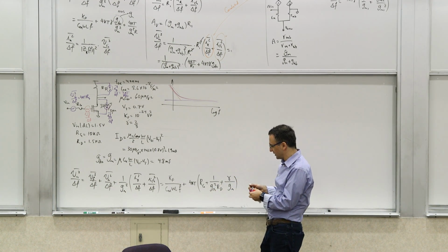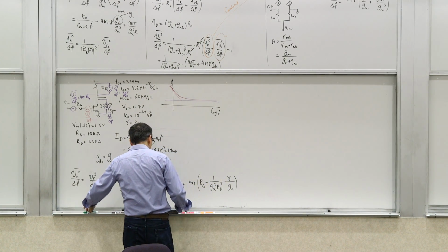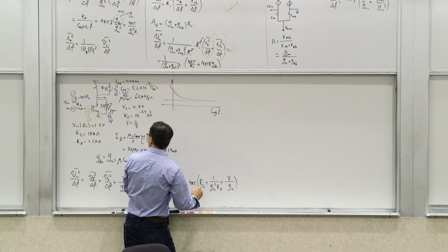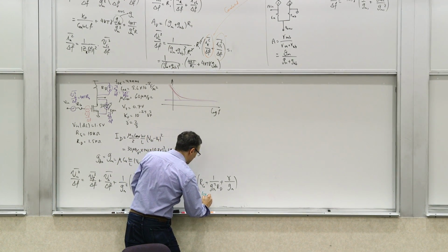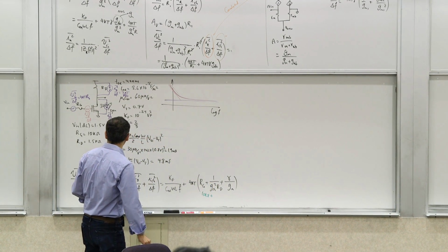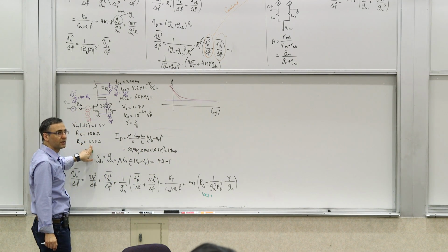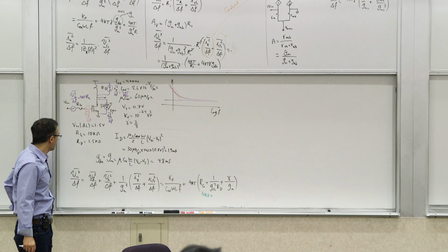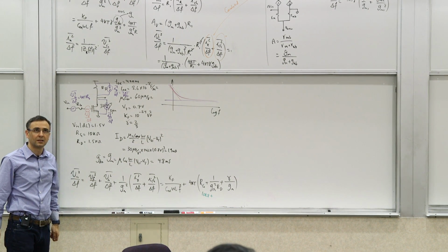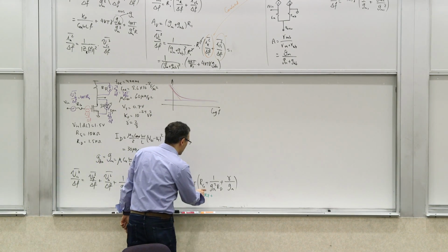Let's just do a quick calculation, right? Because we know the parameters, the numbers. So let's see. If we have these three things, what was RG? We said it's pretty large, right? 10 kilo ohms. Now, what is this quantity, GMRD, the gain? 4.8 times 1.5 kilo ohms, so it's 7.2, right? So it's a gain of 7.2.